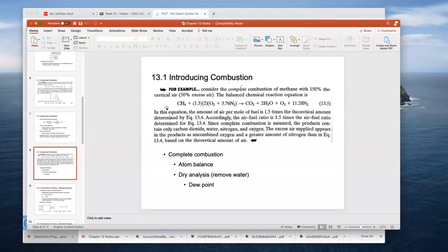Now, the other term that is going to be discussed on Thursday is what's called the combustion heat. Combustion heat is if you came in with the left-hand side here and you allowed the right-hand side to come out at 25 C or 77 Fahrenheit. The question is how much heat has to be released in order for the products to come out at that lower temperature.